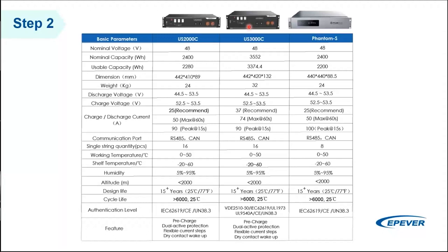And if your charge controller or inverter is capable of connecting to the battery, then it will be much better, because then your profile would be smart and based on what the batteries need. And they normally have high life cycles. For instance, this manufacturer claims about 6,000 cycles with 95% DOD, which is extremely high. It's going to last, for example, for 15 or 16 years.